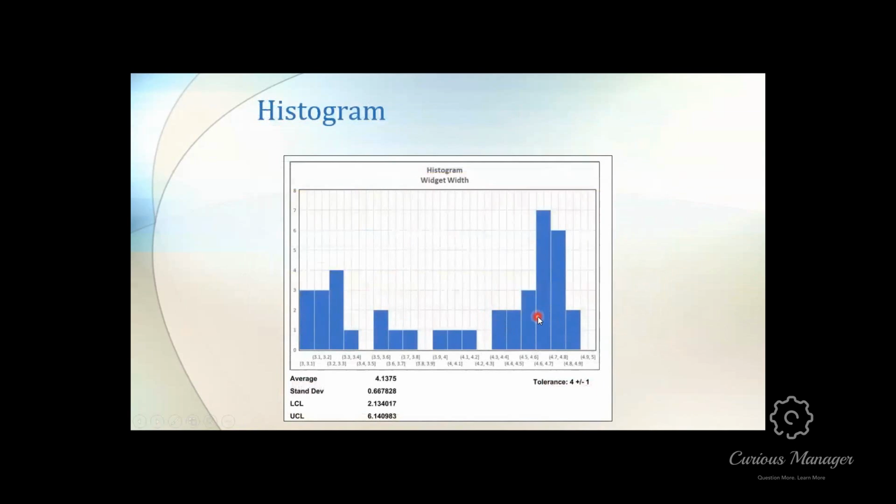What it could be is that these parts are showing up to the assembly outside of statistical control, outside of the specification limits, but they're being worked so that they just barely fit inside the specification limits. This is when you have people intentionally having to fix things. This is when you have rework demand, which I'm going to talk about, types of demand in the system, in a minute. So you have people reworking the materials so that they fit inside this band here.